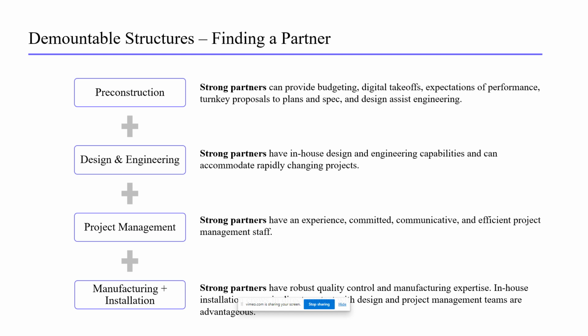Therefore, the pre-construction phase is arguably the most important because in this phase, the most efficient design can be agreed upon according to the project design requirements and, very importantly, the budget demands. While some of these details can be determined later in the bidding process or even the execution phase, experience has shown that this increases the budget, opens the manufacturing and installation phase to a higher degree of risk for communication, potential pitfalls, usually in the form of change orders and things that the ownership and the general contractor don't like to see. So, in essence, a successful pre-construction phase leads to these other 3 execution phases being successful.